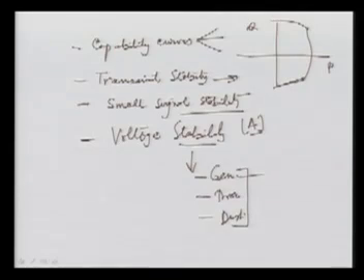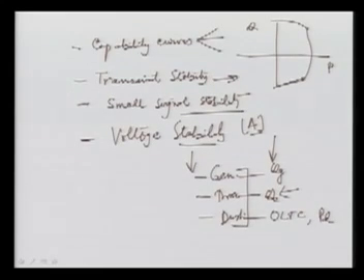Means here we can set the QGs at generation, here we can go for a Q source or some capacitor or static var compensator, here we can go for the OLTC and as well as the P demand if you can go for it. So these are the various control measures by which we can improve the voltage stability of the system.